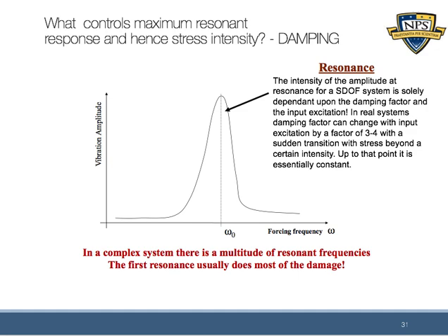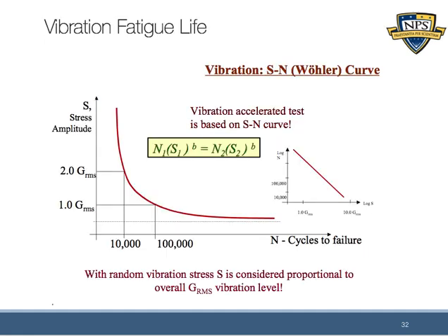And that's when the forcing function of the test itself, which is vibrating the unit, works in unison with the frequency of the unit, and as a result, the two work to grow uncontrollably, and that's when you have a lot of damage. And so there's no damping in that situation, or usually not enough to save the system. And so identifying natural frequencies is usually a very important thing.